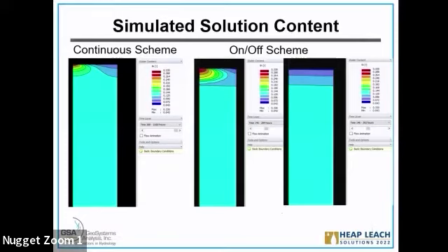And this is showing just a vertical profile. As shown on the left is a continuous scheme. The model does not handle collapse or consolidation, so they just consistently grade. But you see there's a constant pattern, but reality is not like that, because in reality, like I showed in the picture in the earlier test work, they keep collapsing and they generate preferential flow.